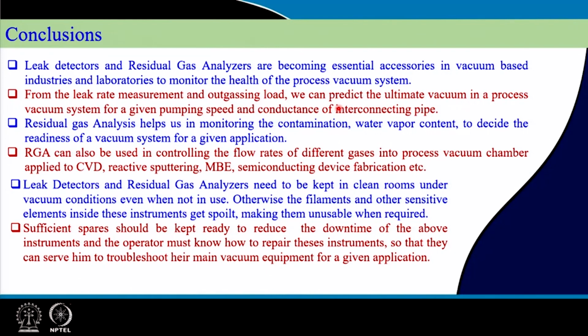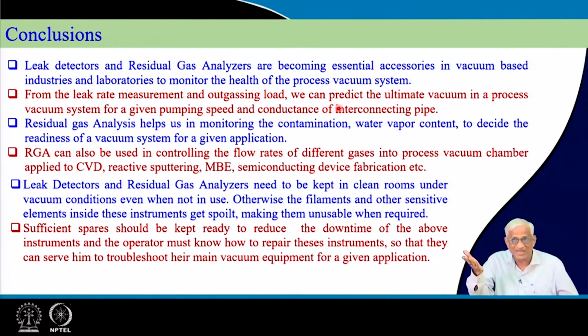That is why I have included it in troubleshooting, but later in the application areas I will introduce it as a chemical signature of the process going on. Okay. We will see that. Residual gas analysis is also useful for contamination in semiconductors, vapor contents, water contents, etc. That way it is used in CVD and high vacuum molecular beam epitaxy, etc. So, you will know whether you are coating properly or something else is coming.